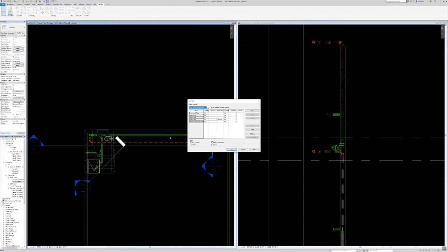When you're doing offsets, it sometimes can be annoying because your offset will be 50mm below the view range, and that stack will still show up in the drawing below, which means you have to hide it. Oh well, it's not much harder to do that than to always change view ranges. Otherwise you're having a hell of a lot of problems with view ranges. To avoid the view range, other people make another copy of the same floor plan and draw the vents on that, and only the vents.